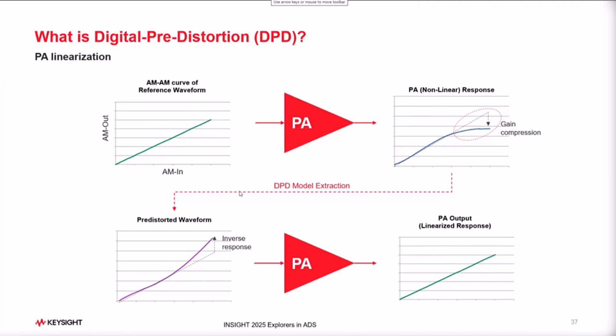All right, so that's how DPD works. But again, like everything, it has its own sweet spot. It works in a particular power range where linearity will be best improved. Beyond that, it will not improve. Below a certain point, it will not improve. Once you know your PA operating point, you can always use different DPD strategies to do that.